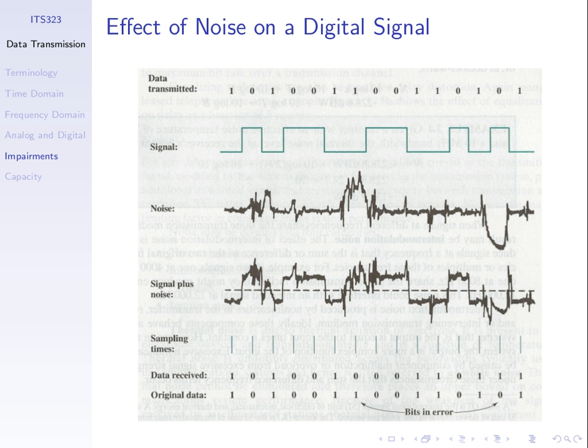And similarly, it goes okay until the second to last bit, again because this large negative spike of noise here changes our bit 0 into a bit 1. The larger the noise, the more chance of errors in our received signal. That's what we see. We see these large random impulses of noise cause errors. Of course, it depends upon the amount of noise and upon the transmitted signal. But in general, the more noise, the more chance of errors.